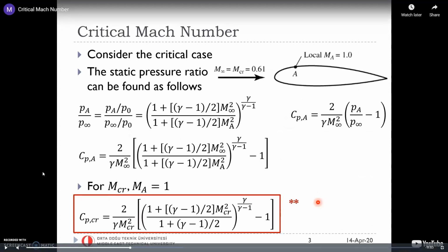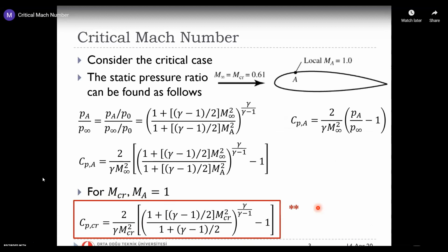Is the critical Mach number for any airfoil defined in the zero angle of attack situation? Good question. Actually, it changes with angle of attack. Right now, for initial introduction purposes, we are discussing zero angle of attack. However, as you very well know, as we increase the angle of attack, the value of the minimum pressure changes, so the amount of acceleration also changes. So the angle of attack does influence the critical Mach number.